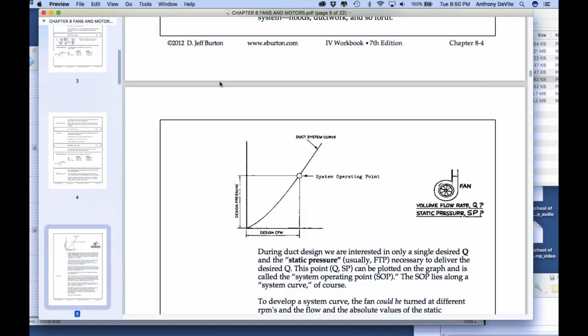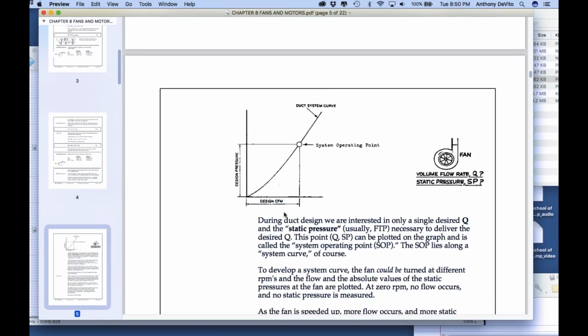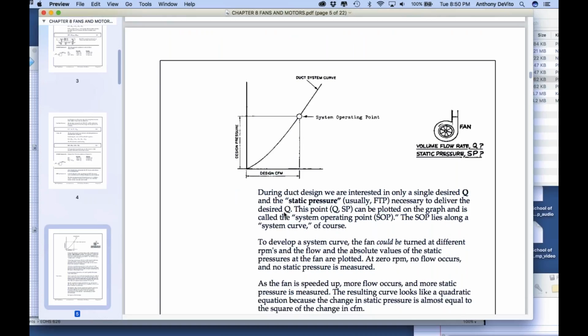for the most part, though, you're taking that contaminant and pushing it out of the building, out of the space, right? So it's usually going out of the building. Okay, so now we need to select a fan that's going to deliver the fan total pressure that we need and move the quantity of air that we need, right?